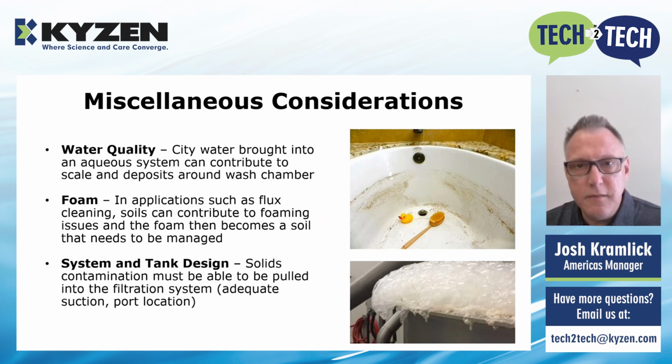And finally, here, system and tank design. Solids contamination must be able to be pulled into the filtration system. This means adequate suction and careful consideration of port locations in the tank. We have numerous customer examples where solids contamination lays on the bottom of the tank and perhaps on an ultrasonic radiating surface, and that soil continues to degrade and may reduce in particle size and therefore escape the filtration system.